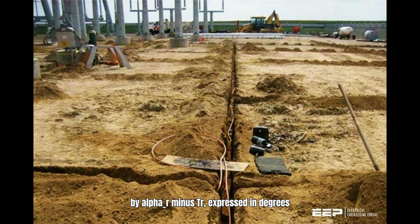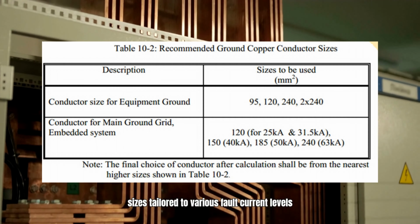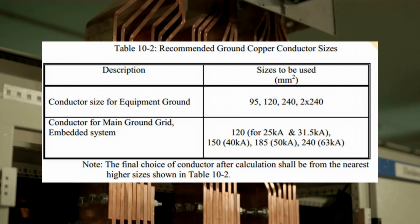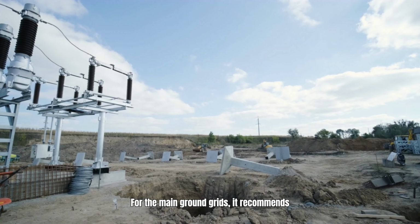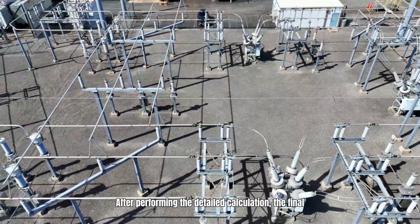Applying these precise parameters in our example calculation yields a required conductor size of 150 square millimeters specifically for the 40 kA fault current scenario. Table 10.2 offers recommended ground copper conductor sizes tailored to various fault current levels for practical implementation. For the main ground grids, it recommends sizes after performing the detailed calculation.